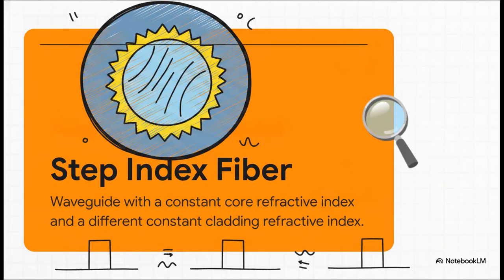So, a step-index fiber is basically at its core an optical waveguide. But why do we call it a step-index? Well, it all comes down to how it controls the light. The fiber has this central core with a constant refractive index, and it's wrapped in an outer protective layer we call the cladding, which has a completely different constant refractive index. And that word step literally refers to the sudden, abrupt jump in the refractive index right at the exact boundary where the core meets the cladding. There's no gradual fade here, it is just an immediate, sharp step.